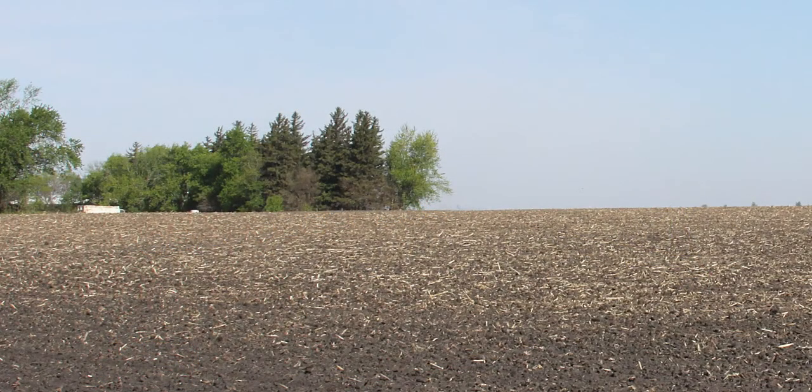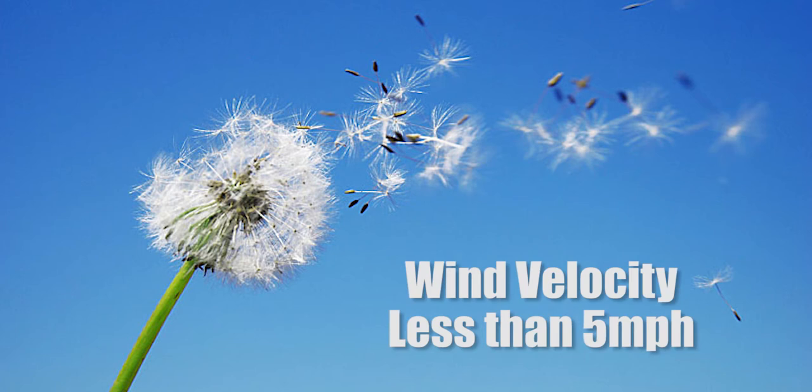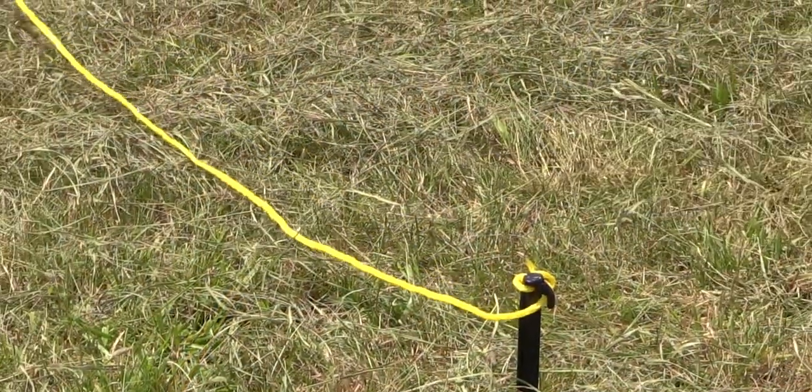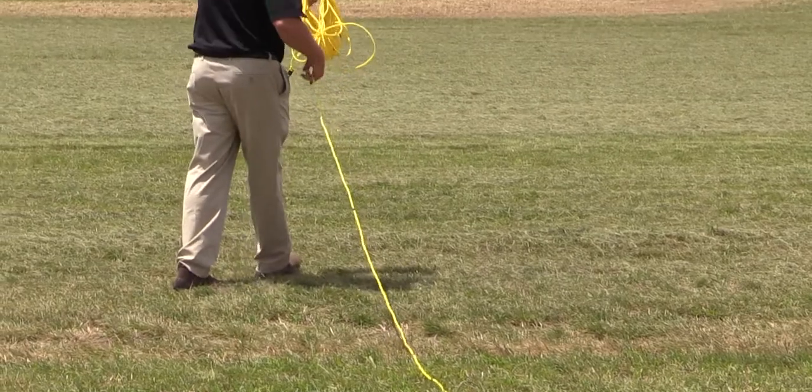Before beginning the test procedure, select an area that is approximately 120 feet by 400 feet and has a slope of less than 2 degrees. All testing should be performed when the wind velocity is less than 5 miles per hour. If wind is present, testing must be done with the spreader traveling parallel, within plus or minus 15 degrees, to the wind direction.